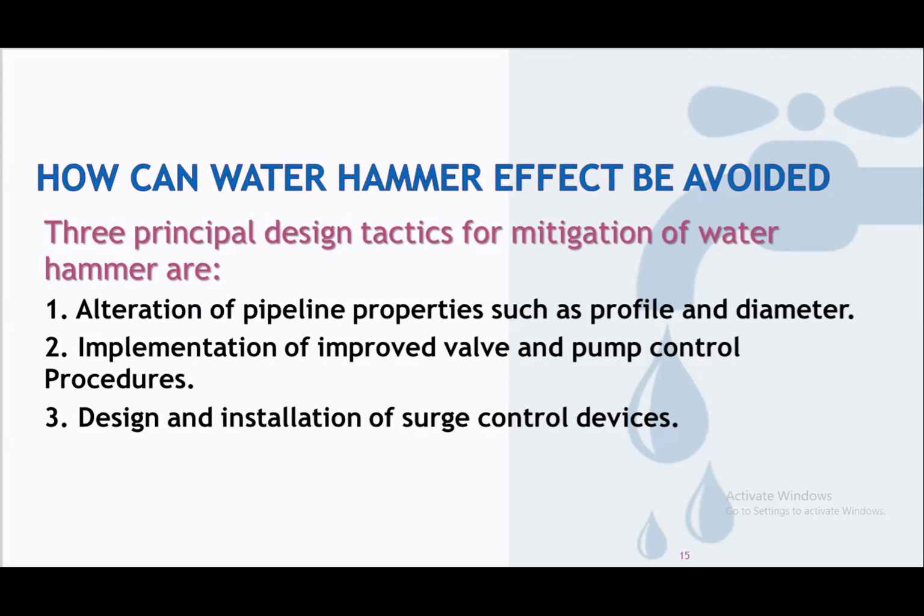When we try to put in and size the control devices, as a beginner, we try to make a simulation for these emergency cases. And after we run a simulation and estimate the value of the water hammer pressures, then we can state what exact control device we can use, what its sizing is, and what is the proper operation of controlling surge pressures.